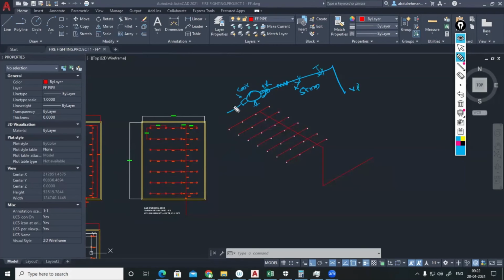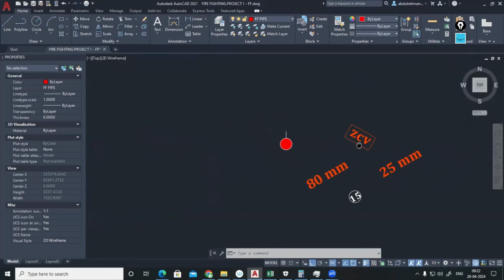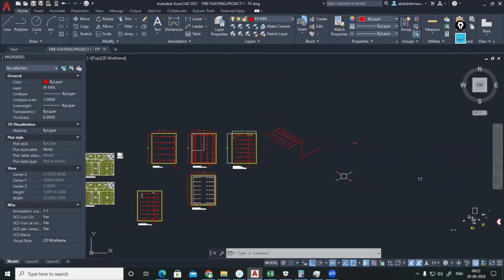Then after that, in the delivery, again we will be having a flexible pipe connector, then an NRV, then an isolation valve, IV. IV is there and NRV is there. Anyhow, minimum 3 I'll be considering now. At least 3 fittings I should consider.